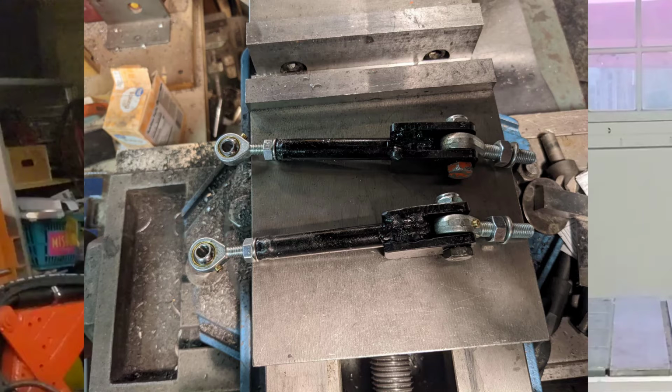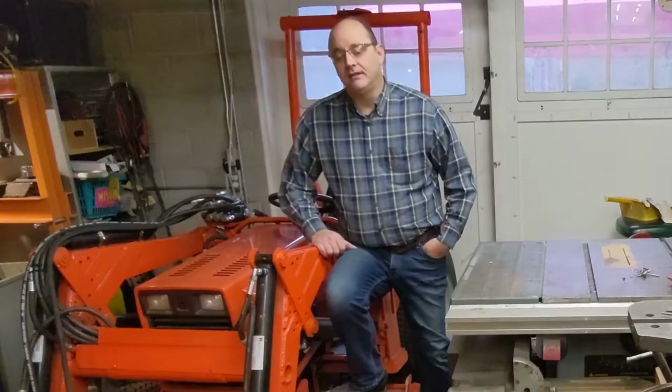While I was doing all the work to remove and reinstall the travel control valve, I went ahead and fabricated a new set of mechanical linkage from the travel lever to the valve. The linkage is a common wear item, and using ball bearings holds up better than the factory ball swivel joint design. It's also time to make the final decision regarding the paths for the hydraulic pressure and return flows. Now, because we're redirecting the main pressure feed line, we're essentially redesigning the entire system.